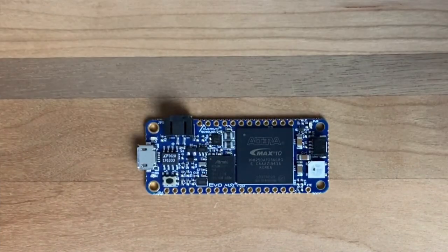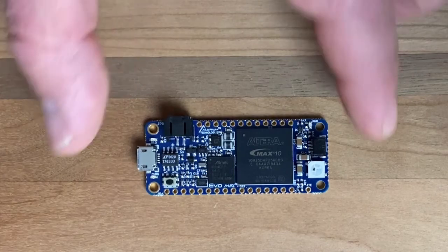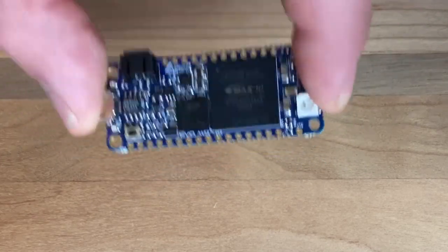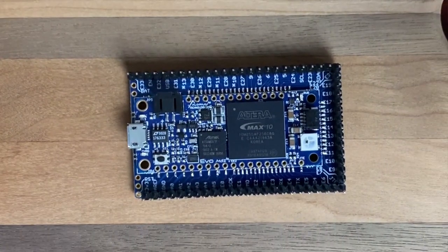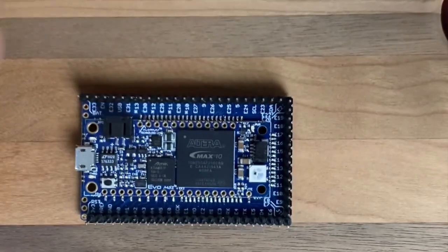It's basically a breakout board for Evo M51, because if you look around the edges of Evo, you can see that we've got these castellated vias. And we'll try to zoom in on that on the camera when we get a chance. It's one of the unique things about this board, it allows you to solder it down directly as a module. Now, there are what we call interstitial castellated vias. So in between each one of those vias, there's a castellated via with each hole, but then there's some in between as well, which gives you a bunch of extra I/O that you can use. That's really convenient when you're mounting it down inside of a project, but if you want to do some development with it, it's not as easy to use. So we have this Evo tray board that allows you to mount it on there, and that's what I'm using for this video.